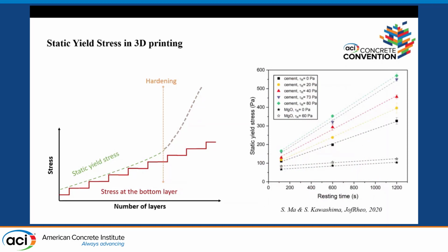Now there has been work that started to look at what's happening to the rheology, and what's happening colloidally and for the rigid structure during the stress period. So when I place my cement here and it's under sustained stress on top of it, what's happening to the rheology of cement? There has been some work that looked at plain cement systems, and it basically showed that